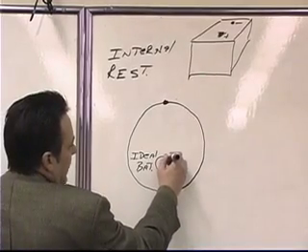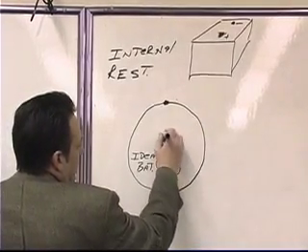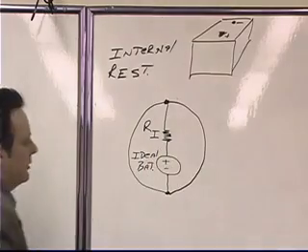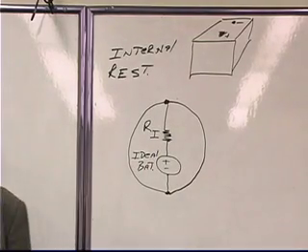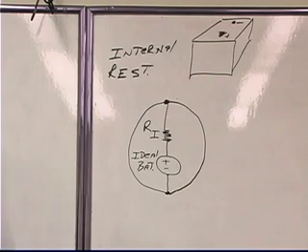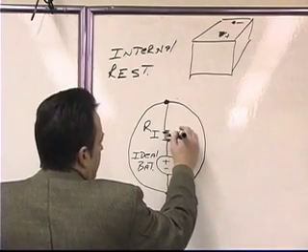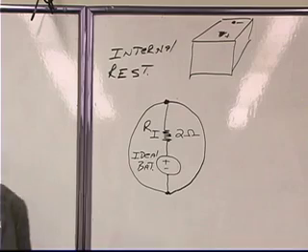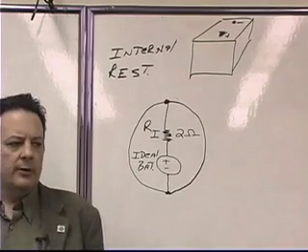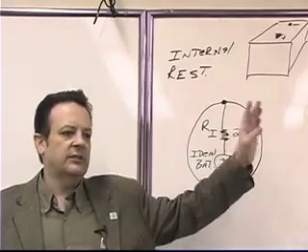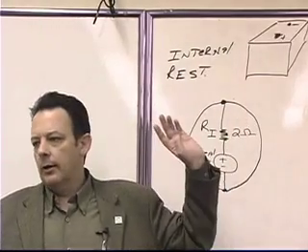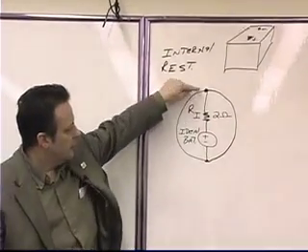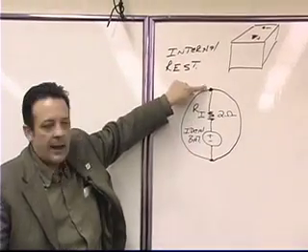Then in series with the ideal battery is a resistor, and that's our internal resistor. So I'll just label it R sub I for resistance internal. And we're going to give it a typical value. We're going to say that the internal resistance of our battery is 2 ohms. Then we're going to see how the loading effect, or hooking up successive hair dryers, space heaters, blow dryers, whatever, has an effect on the voltage that we read at the output terminals of our actual battery.